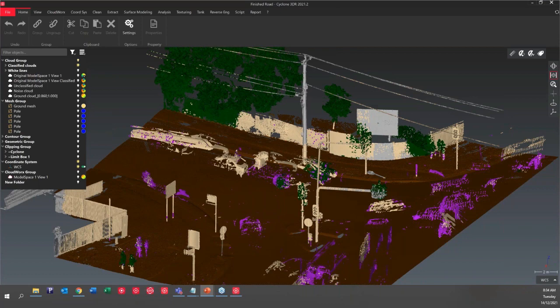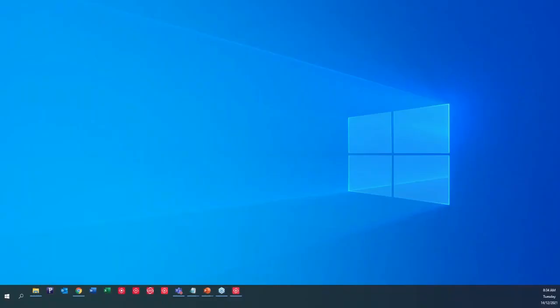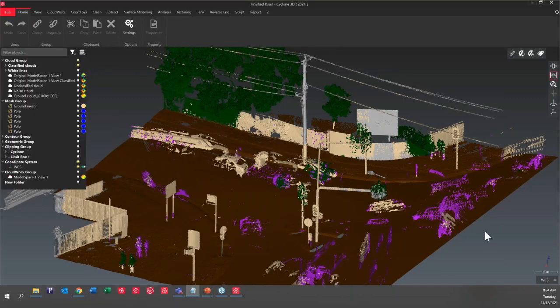I don't pretend to know exactly how it works. But what we've seen is it does a really nice job on the road and the UAV data sets. It's excellent at getting that ground surface quite accurately. And then anything above it, as we saw, the trees were classified as buildings. So there's a bit of manual work to get those classified objects correct, but there's a tool there that allows you to do it. But essentially, if you're going for a road surface or a terrain surface, there's not a lot of manual editing required from our experience. So that's a quick comment on that.